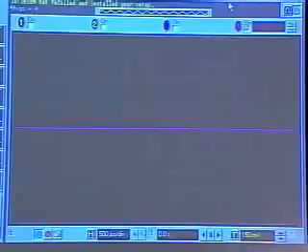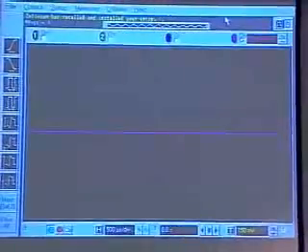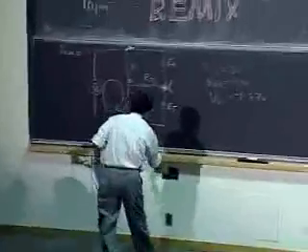But more interestingly, I can show you the same thing by holding this current measuring probe directly across that node, and notice that the net current that is entering into this node here is 0. So that should just show you that KCL does indeed hold in practice, and it is not just a figment of our imaginations.